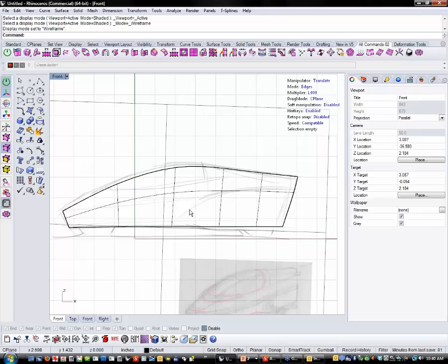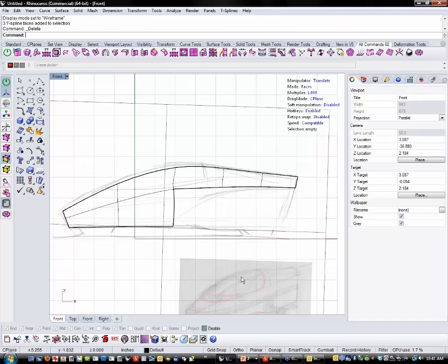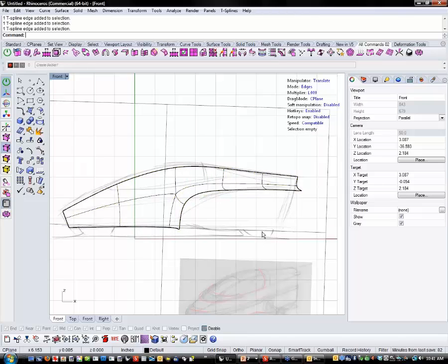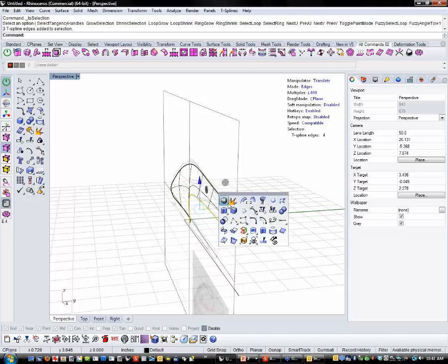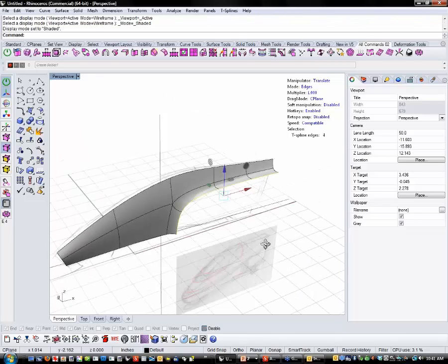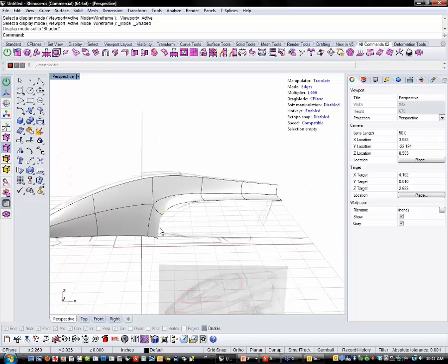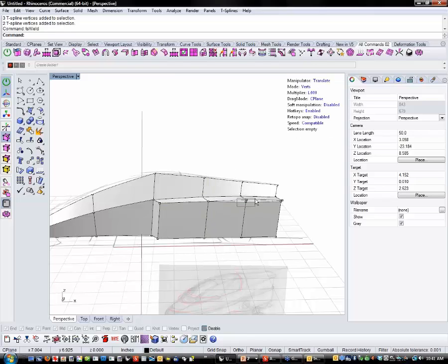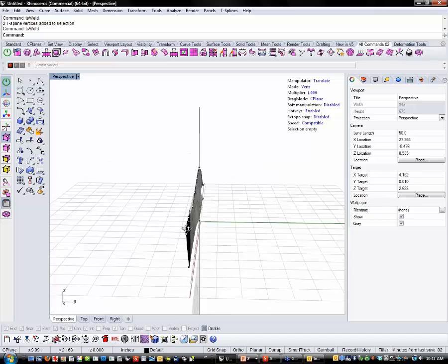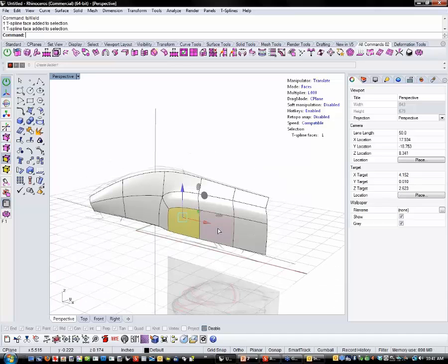Now there's two ways I can do that. I can do it like Sky was talking about, where we actually add a fender, and the way to do that would be to grab these faces and delete them, and then grab these edges and extrude them. Okay? Now you can see this is starting to develop into a fender. And then to complete this, I'm just going to go 1, 2, 3, so that these all line up. And I'm going to weld, weld, weld, and I've got my fender shape.